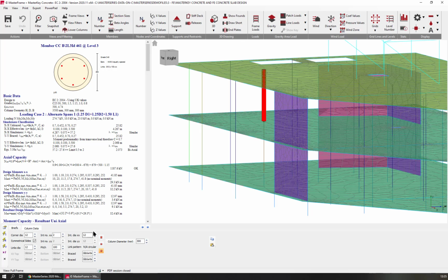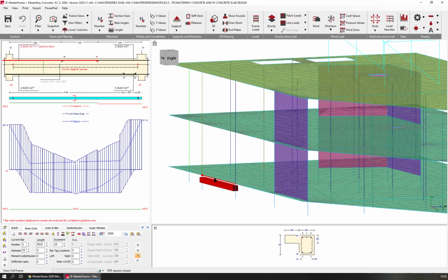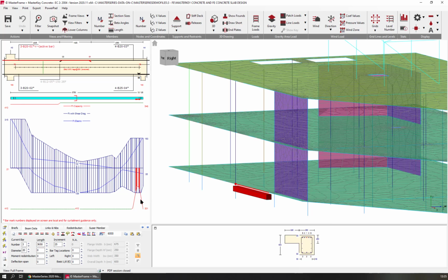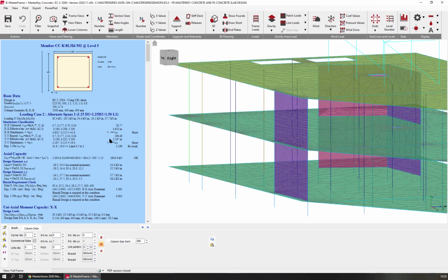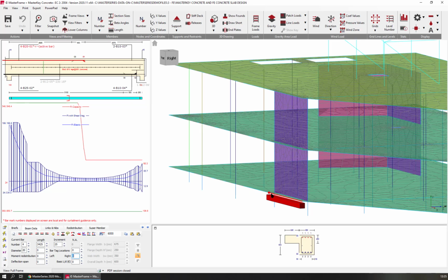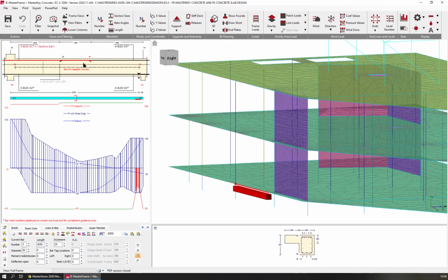It's now giving us the same 6 bars at 1200. So that's your beams and your columns all being designed for you. And of course we can take these and send them out. In this case we got a little problem here just with the lapping of the reinforcement for the next span, which we can look at and take that, and there we go. And it's just saying no, I'm unhappy down here with these bars. That's better, and there we go.